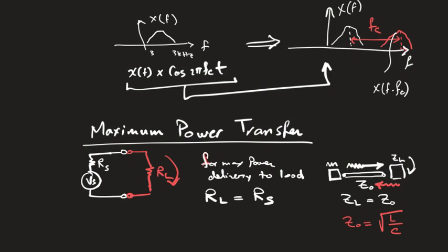So each one of those has a representation for L and C, which is the inductance per unit length and the capacitance per unit length, right? It has a representation for each one of those, different in terms of the dimensions, the geometry, and the material, of course, epsilon naught, and so on, right? And eventually, Z naught was the root of this divided by this. So eventually, you can find Z naught in terms of the geometry of the transmission line.